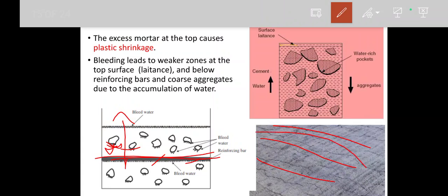See, as soon as you make the concrete, when you come the next day to make arrangements for curing, you can see long cracks along the length of the slab. The owner, if he sees it, will be suddenly shocked. Why is this crack appearing? That is all due to the excessive water adding. It comes to the top surface like bleeding, and in the direction of wind, in the presence of low humidity and the high temperature of the sun. These are the factors which make this type of plastic shrinkage crack.